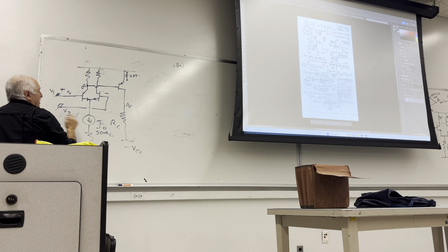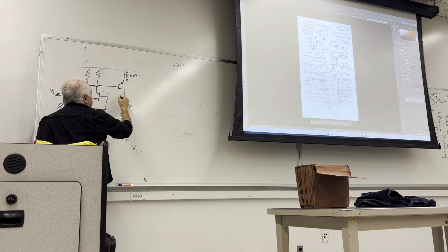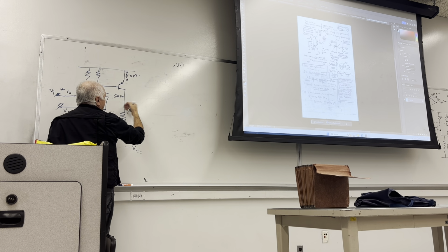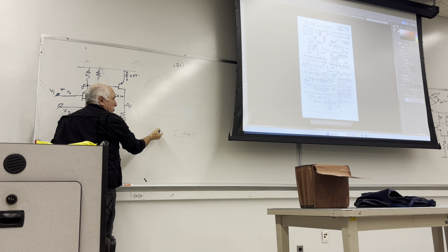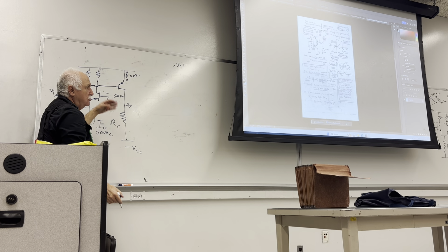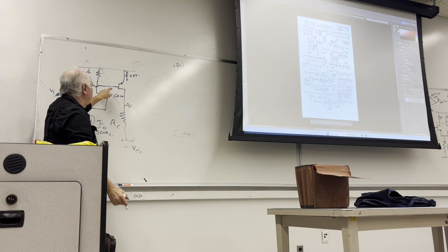The amplifier that we have built provides gain. RC is the output resistance if you try to connect that directly to a load. We can't do that because these RCs are very high in order to obtain a high voltage gain from that stage.